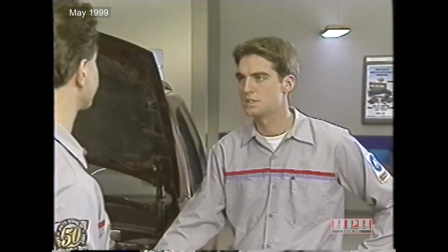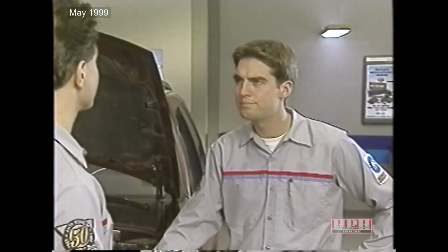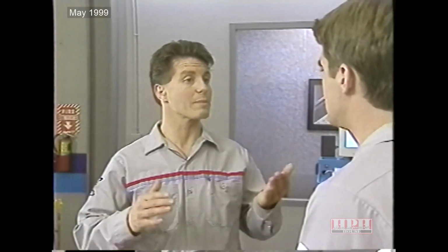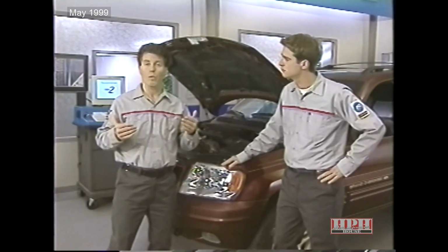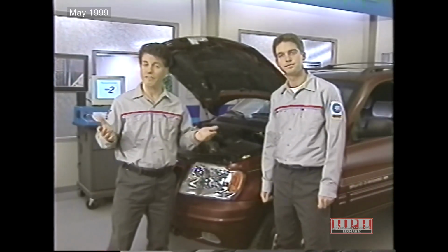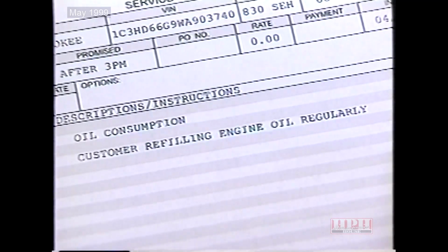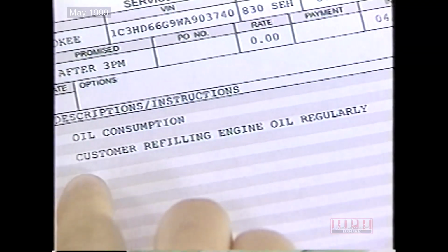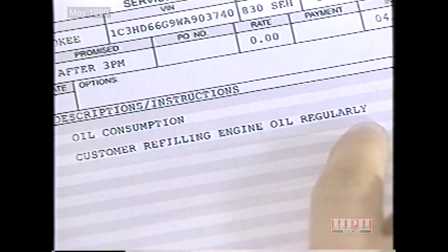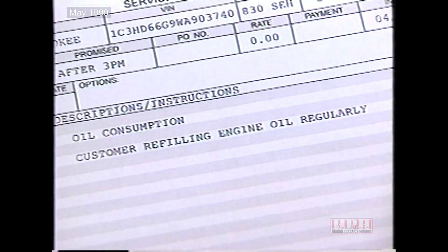Now what, Chris? We want to find out where it's coming from? Well, not quite yet. Before we look for the leak, we want to determine what type of fluid is leaking, whether it's engine oil, transmission fluid, and so forth. This way we won't waste our time looking in the wrong area of the vehicle. You can start by checking the work order for any mention of fluid level history. If the customer has constantly topped off a specific fluid, it may be noted there.